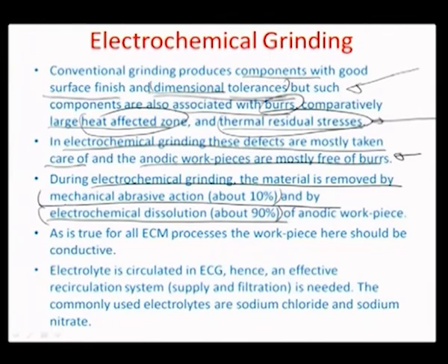So one very important and significant aspect of ECG is that the workpiece and the grinding tool both have to be conductive in nature, because it's an electron flow process. So you cannot have one of the components non-conductive, or insulating in nature.